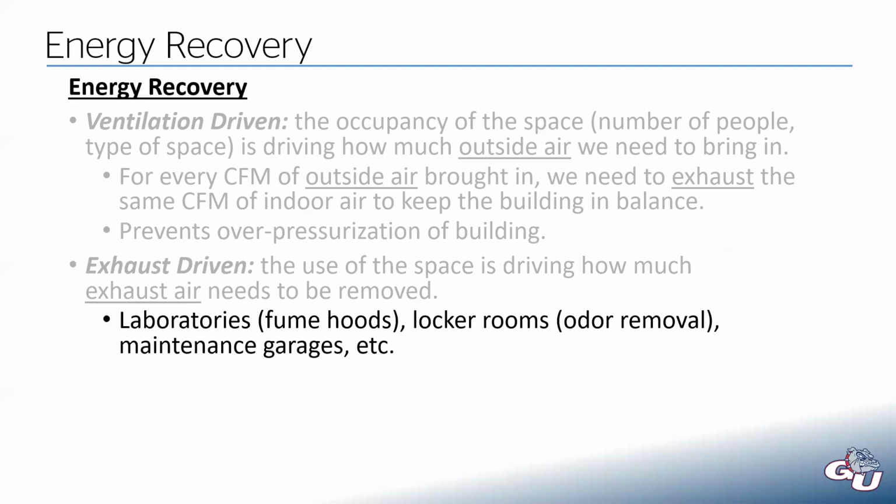You're trying to remove the restroom odors, or you could have a maintenance garage. We looked at that Spokane Transit Authority building that McKinstry worked on a couple weeks back, and that would be an example of an exhaust driven system, because in that system we had to exhaust, I think it was 0.75 CFM per square foot of garage.